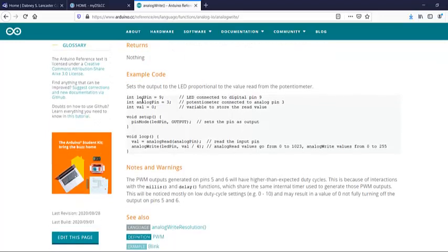So let's see what this does. We have an LED pin 9, an analog pin 3, a value of 0. It defines pin 9 as an output pin. Now, pin 3, it says analog pin is 3. It doesn't use a pin mode. It turns out for analogs, you don't need to specify.